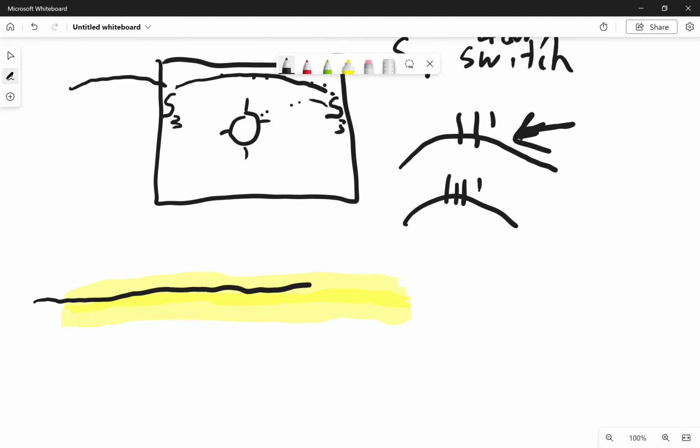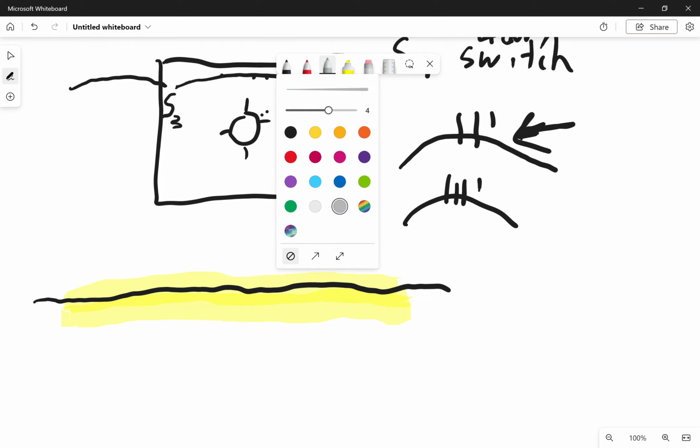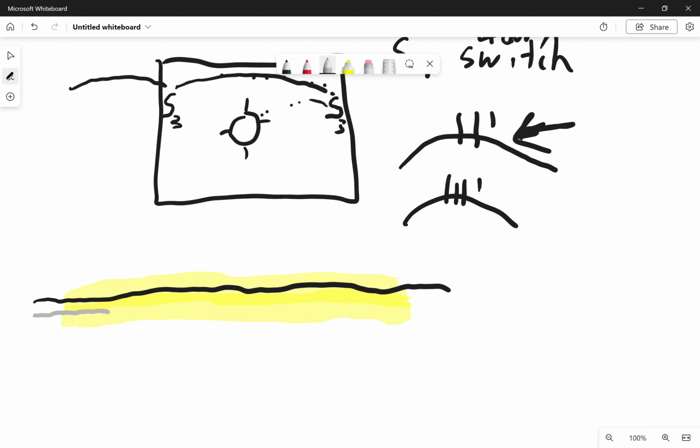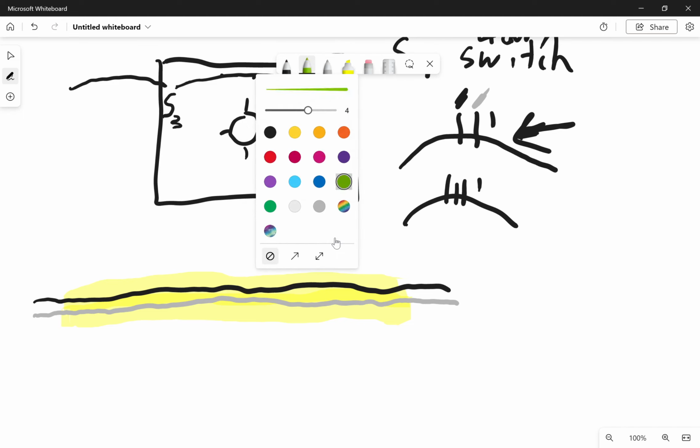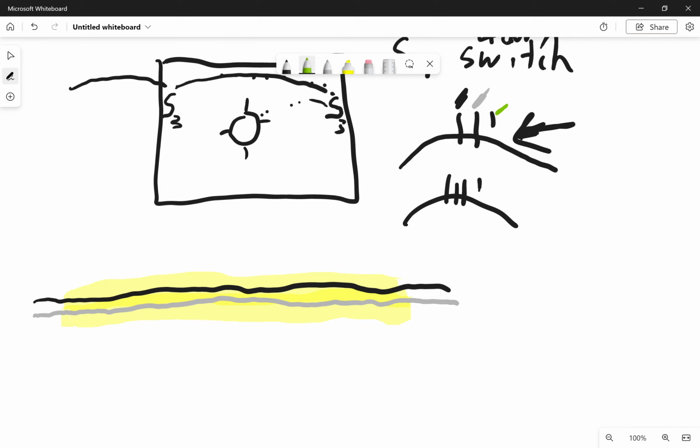One of those is going to be your black wire, right? The other, right, I'm going to do this in gray, but it would be white. White's not going to show up on my drawing here, so we're going to use gray in all of these to represent white. So our white wire, it's also considered a current carrying conductor because it's carrying the current back to the source. We'll show you how that works here in just a moment. And then so that takes care of our current carrying conductors, right? We've got 1, 2 current carrying conductors, and then there will be a bare copper, right?